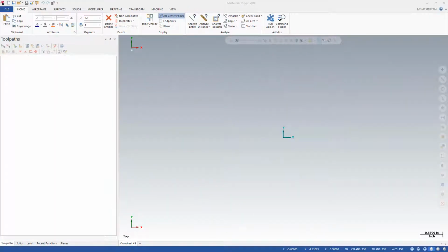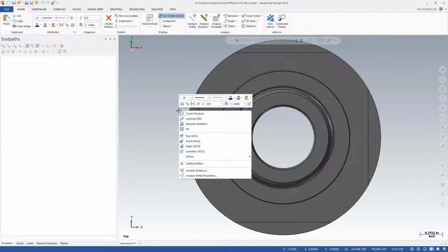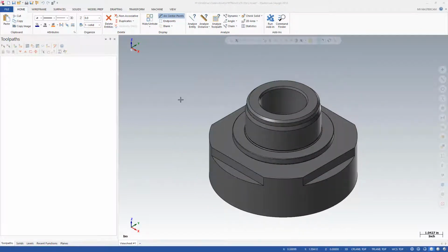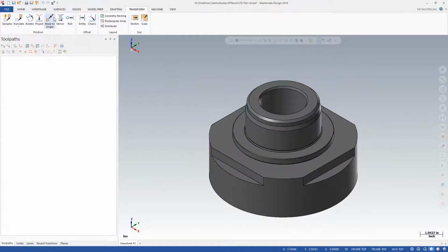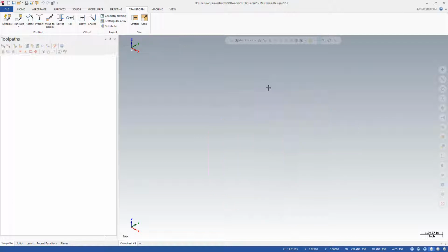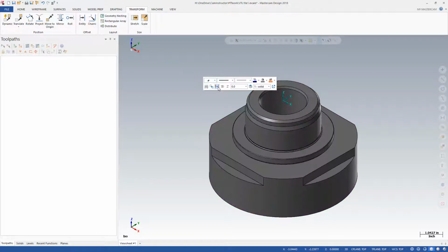Using the following workflow, standard planes can be used for milling if the turning plane is created as follows. Import the part and align so the top plane's XY origin is centered along the axis of rotation for the turned feature. Z location can be placed as desired.